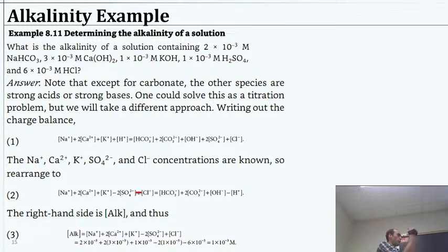But you get the picture of this process, right? I'm not going to spend the minute or two to double check all the algebra right there, but the process was correct, right? We do a charge balance, and we do the sum of the cations minus the sum of the anions, and that is our acid neutralization capacity. Now, these are the cations and anions that are not dealing with anything relating to pH, right? These are the strong acid and strong base cations and anions. Okay, does that make sense?